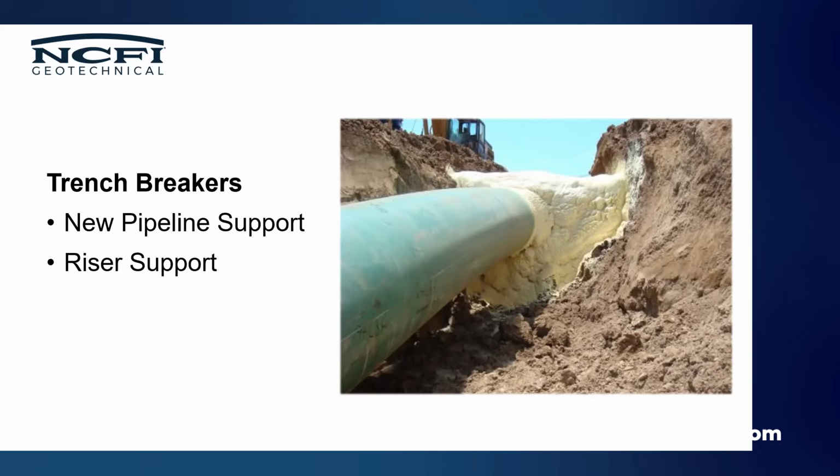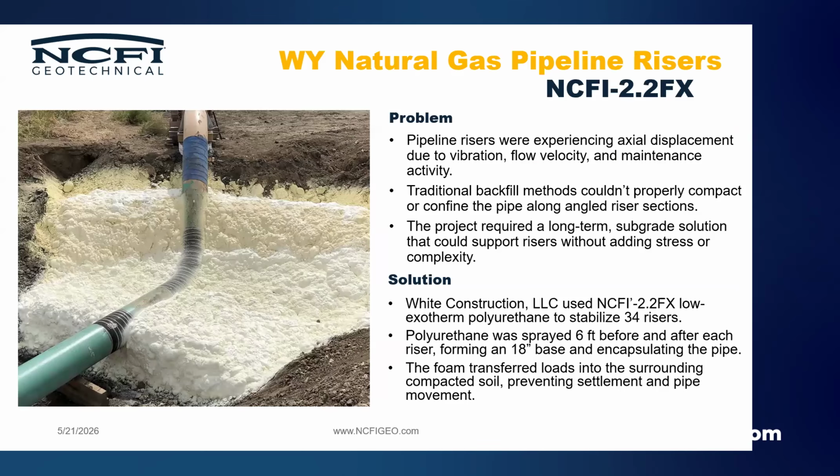Not all the trenches are this shallow. A lot of them are a lot bigger, so it can be kind of dangerous. It can be used for breakers and/or riser supports or pillows, another term we've used, and also for risers like this. It can help stop vibration when you've got this axial displacement here, and then pillows are just used basically where they put cribbing in underneath the pipes when they're putting the pipe in the ground. They'll spray pillows right next to it, then remove the cribbing so that it doesn't rot over time.